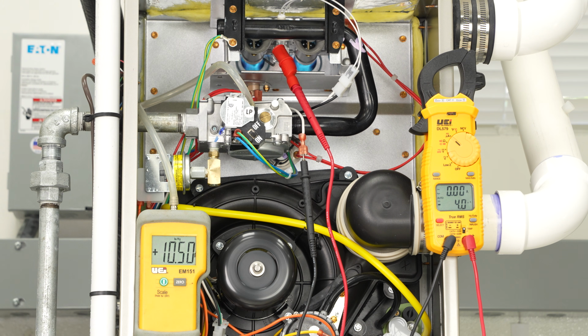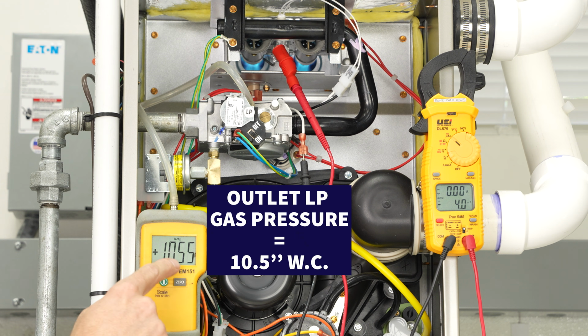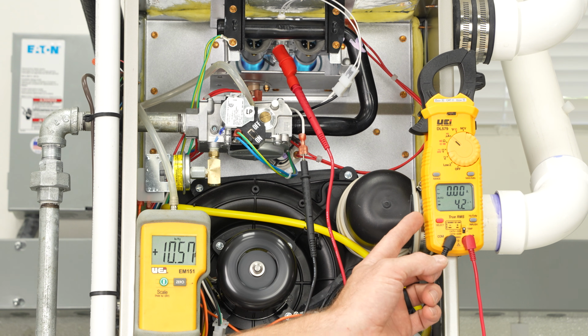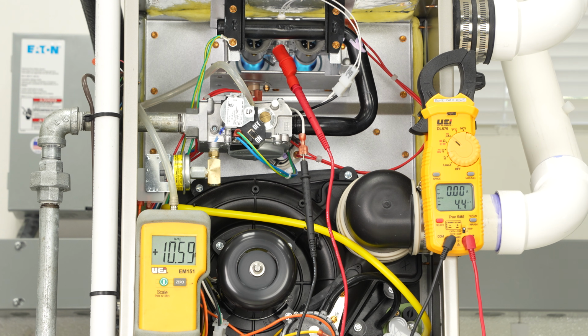So right now our outlet gas pressure, which is measured over here, is 10.5 inches of water column, and that's basically correct for a single stage gas valve. Now over here we're measuring 4.2 DC microamps. And now our blower motor would normally be running, but we have that shut off right now. So your fan motor should be running and basically just blowing the air across that hot heat exchanger.